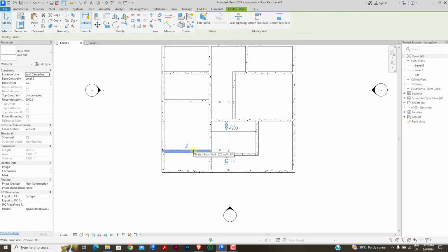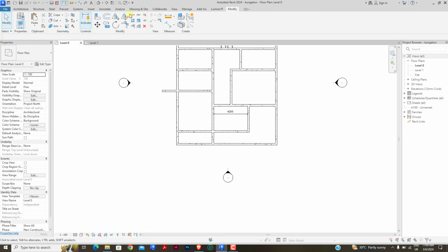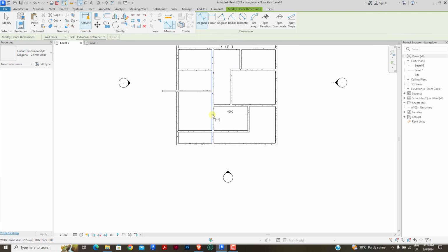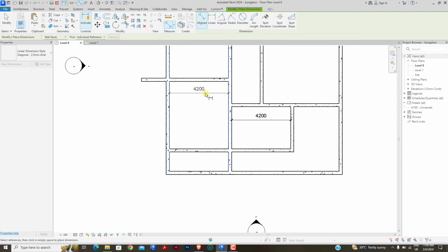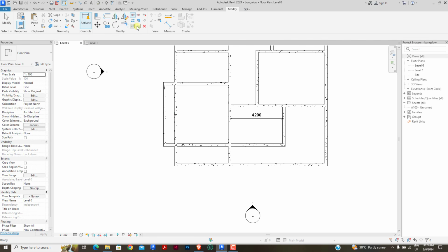Okay, let's just do this. Let's use this dining wall. Okay, so this will be our kitchen space. Let's increase this kitchen, make this kitchen a little bigger. So we have, this is 4,2. Okay, let's make it 5,1. So 5,325. Okay, so we'll trim this. Okay, let's split this wall, trim and extend it to this point. Do the same thing for this.